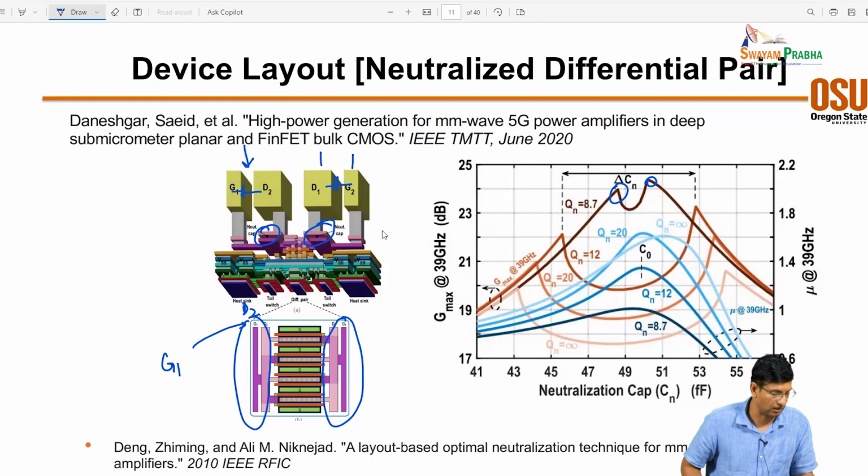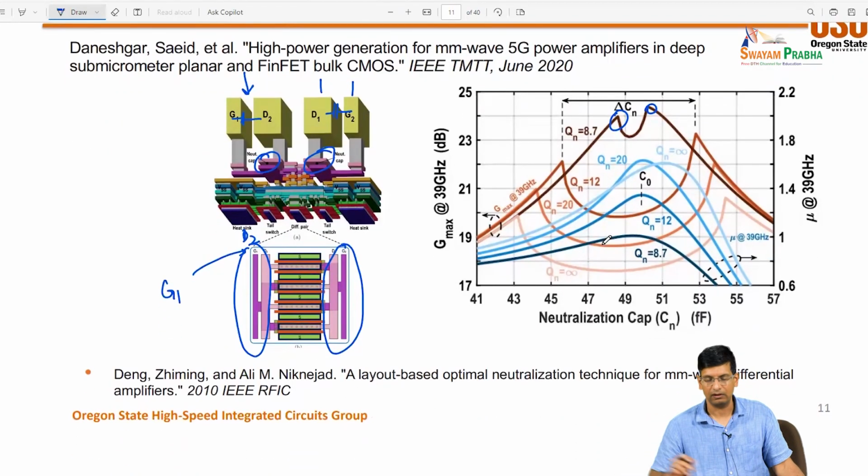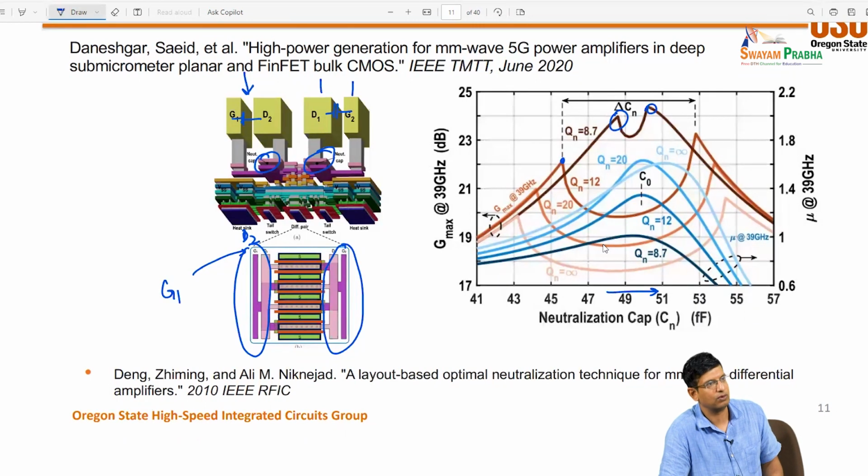So you can effectively design to pick a particular design point that will work from a gain target perspective. This won't track process, right? You're relying on metal parasitics to do that. But again, you don't want to be here either, right? What you try to do is pick some value that is over here, within, let's say, 10%, and you can live with that sort of trade-off. So that is a designer approach.